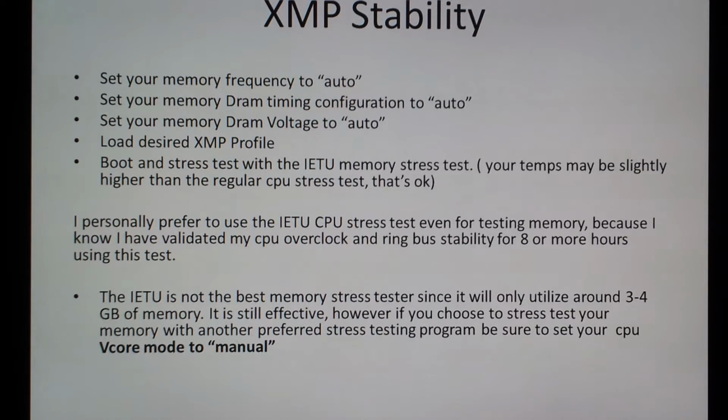Boot and stress test with the Intel Extreme Tuning Utility memory stress test. Your CPU temperatures may be slightly higher than in the regular CPU stress test, and this is okay. You're utilizing a little bit more resources, so the CPU is working a little bit harder, and that's fine. So if through your testing you are averaging certain temps, don't be alarmed if your CPU temperatures increase under the same ambient conditions.